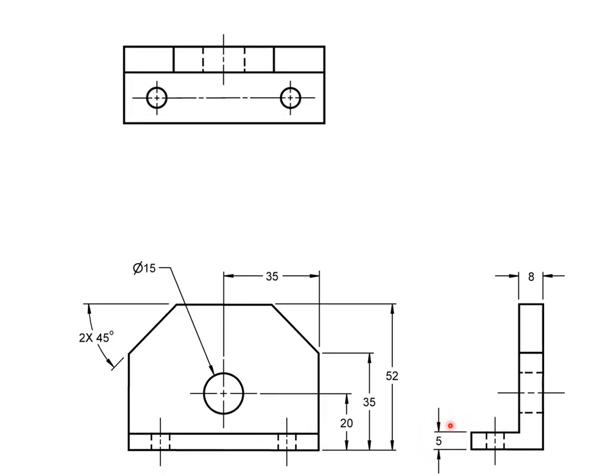even though it's by itself. We also have this wall thickness of 8, so we're dimensioning from back to front, and we're missing the overall depth, so that will show in the top view. But before we go to the top view, let's take a look at the front. We have a chamfer at 45 degrees. Okay, so how is this chamfer located?